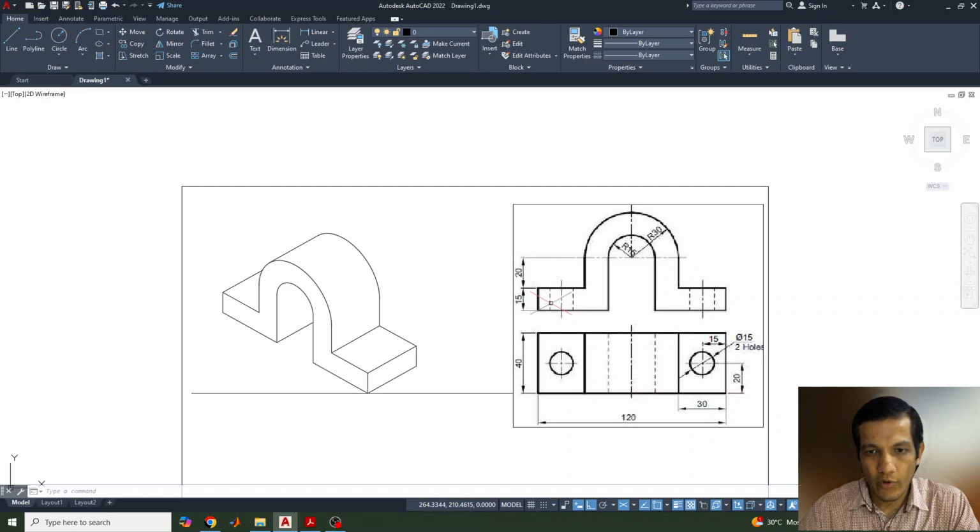these two dotted lines we have not drawn, and those will be visible from the top side. So in the top view, if you see, we can see two dotted lines, this dotted line and this dotted line. That means this small arc which is there will not be visible there, and on that big side we can see only two lines here. So that's why I have drawn it here, no dotted line required for this.